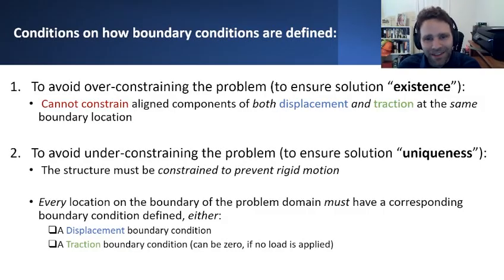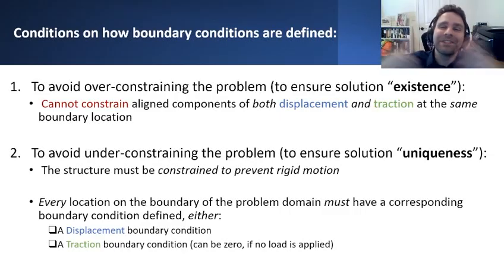we're looking at. If we're non-specific about what the particular traction or displacement is at some kind of missing portion of the boundary, where we're saying, well, I don't know, is there a displacement boundary condition here, or is there a traction there? I don't know. Can we just leave it blank and just try to come up with a solution, and maybe that'll be good enough? Unfortunately, no. We have to be specific, and we have to say whether there is a traction here or whether there's a displacement boundary condition here.